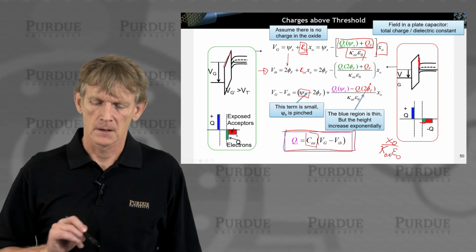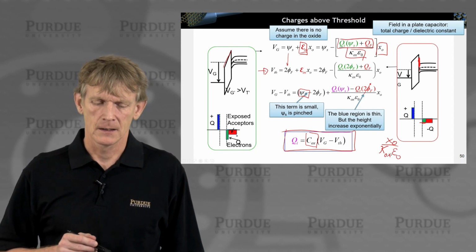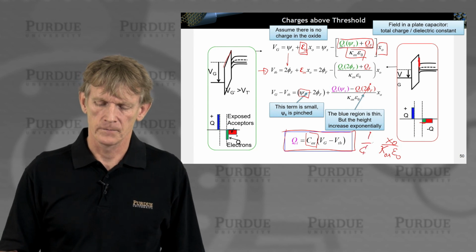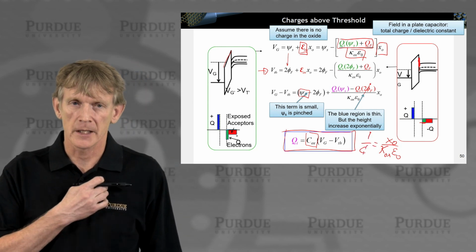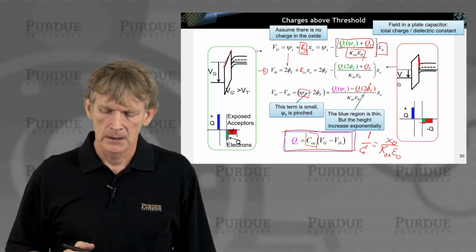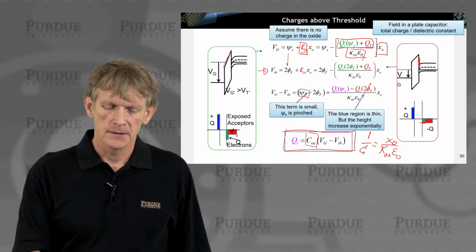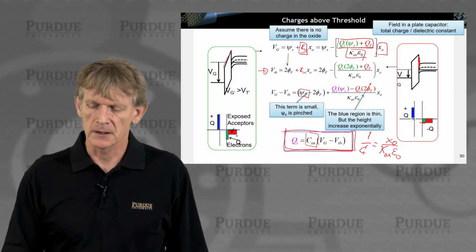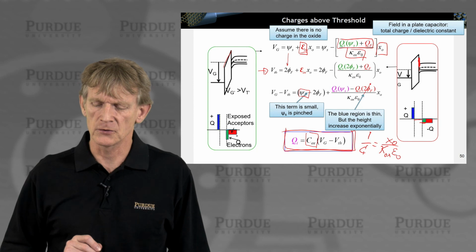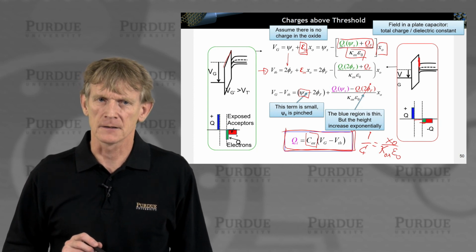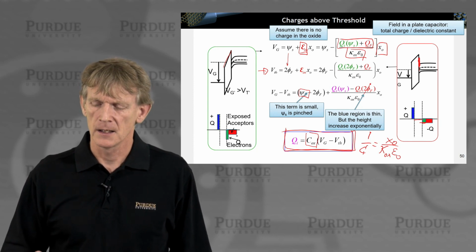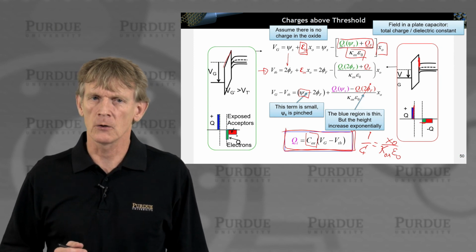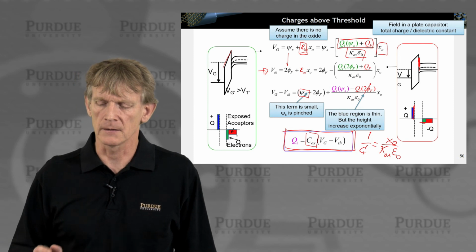That's our oxide 1 over C. The point is that the charge separation that we have here is now completely determined by the oxide thickness. There's no charge in the oxide, and we basically have infinitely thin plates. We no longer have a widely distributed charge.